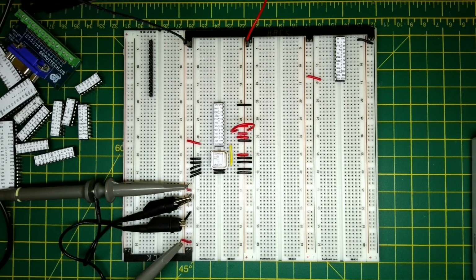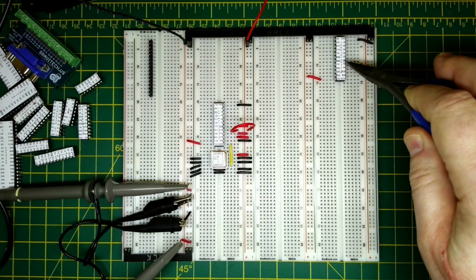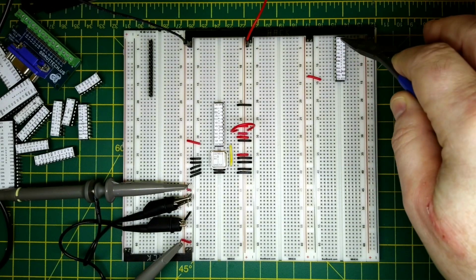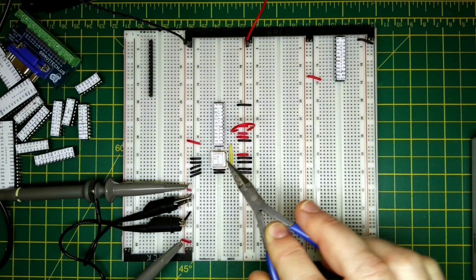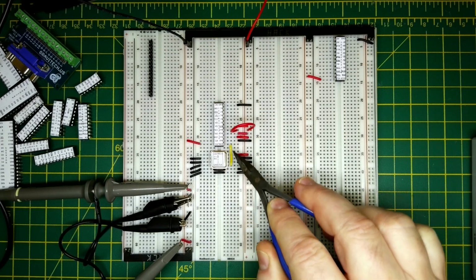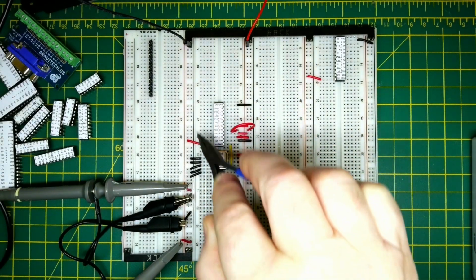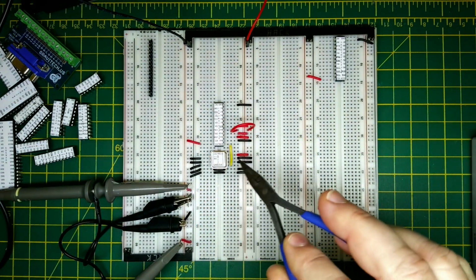So you can see on the top right, this is the IO decoder, which you've kind of tested already in the EPROM programmer test facility. And this is the clock, 25 megahertz clock, the output from the clock going into the PLD, and then all the signals on the left hand side here are largely coming from the clock.